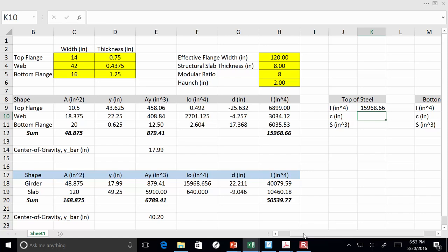You got to account for all of it. What's the total height of the section? It's the thickness of the bottom flange, the web depth, and the thickness of the top flange. So we've got to calculate the total height, then strike off that distance. That'll tell me the extreme fiber. Make sense? All right, so we'll say that thickness plus that, minus that. There we go.